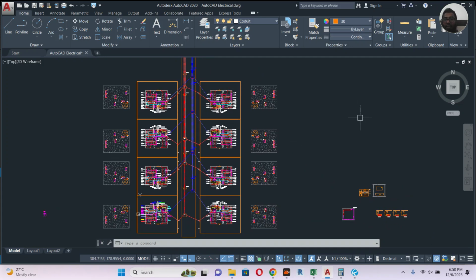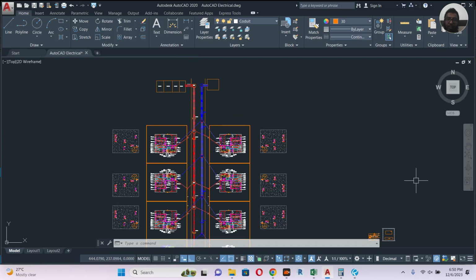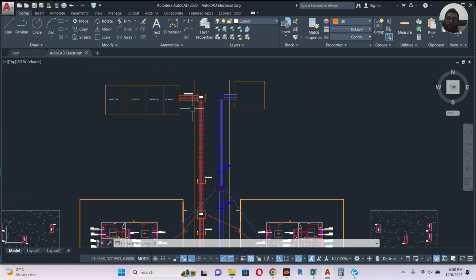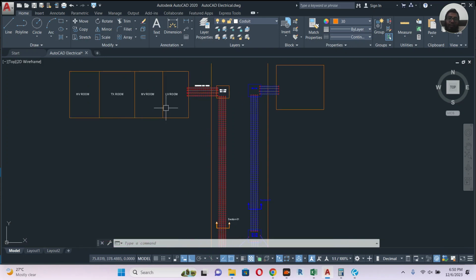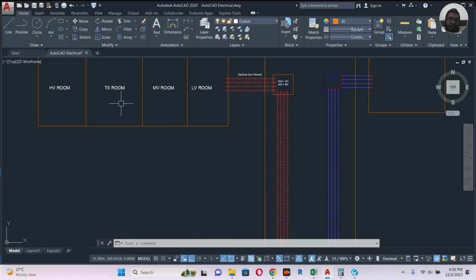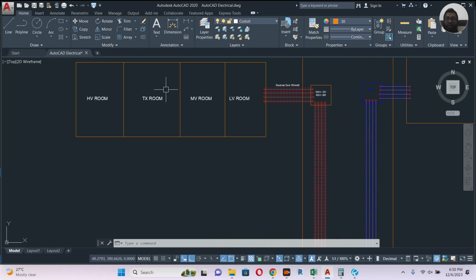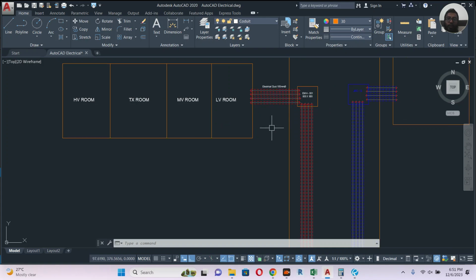Next will be the single line diagram. If you finish this one, then I have to select the SMDB, how much total consuming power, then SMDB to MV, maybe I have 10 SMDB, then MV to transformer. We can calculate the transformer. So I will teach you both, as far as possible. I will teach you accurate calculation and also thumb rule calculation.